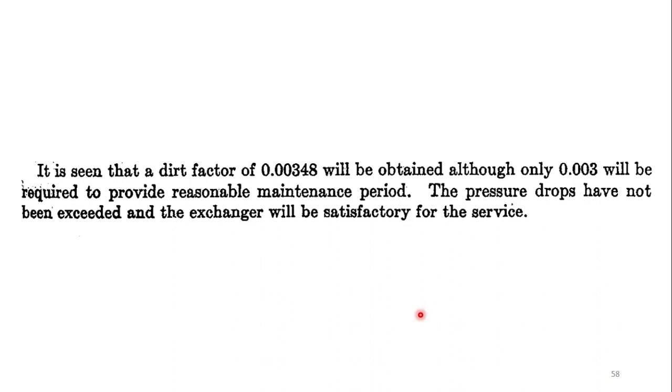It has been seen that the dirt factor that you have calculated is 0.00348, although only 0.003 is required to provide a reasonable maintenance period. The pressure drops have not been exceeded, and the exchanger will be satisfactory for the surface. And with this is the end of the lecture.